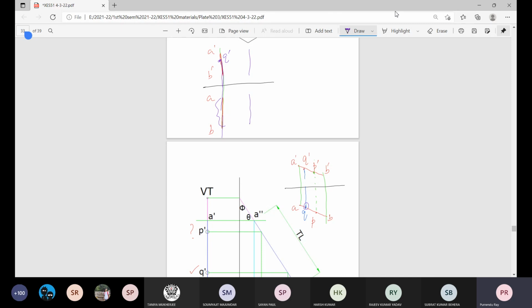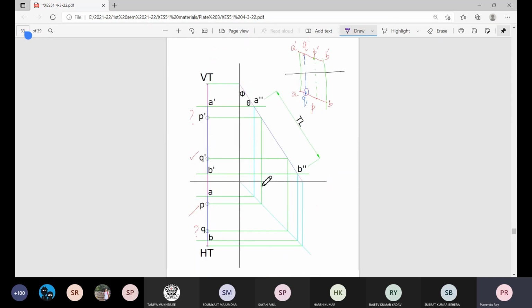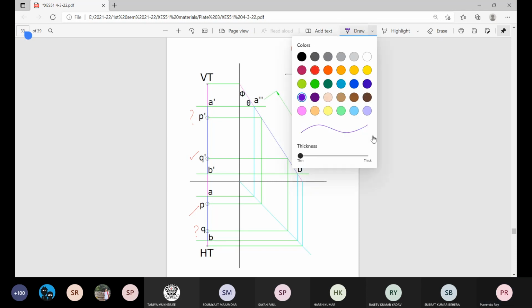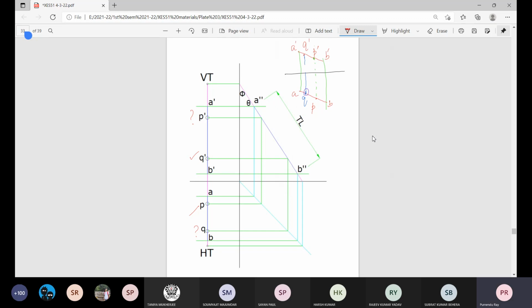But if you think from the other projection, on the pictorial plane projection, there is the side view. P is given. What about its side view? Draw a line through the plane, reach up to this 45-degree line, draw a vertical projector, reach up to this level.